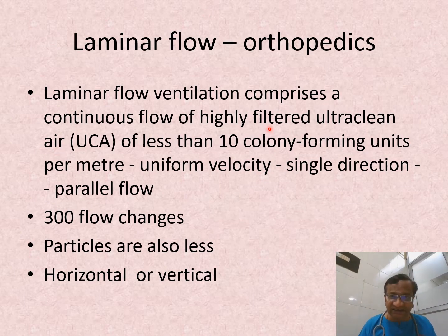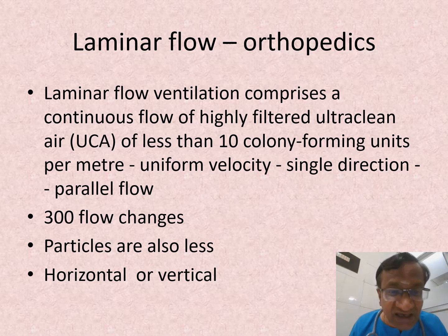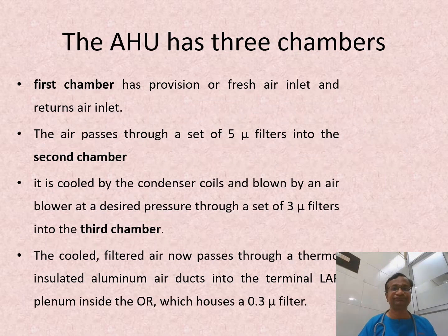Laminar flow comprises a continuous flow of highly ultra clean air, less than 10 colony forming units, uniform velocity, single direction, parallel flow. There are 300 air changes and particles are also less.